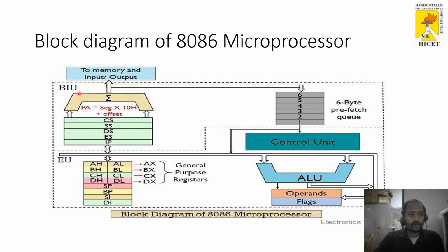Next we discuss the BIU, the bus interface unit, which takes care of all the data and address transfers on the buses for the execution unit, like sending addresses, fetching instructions from the memory, reading data from the ports and memory, as well as writing data to the ports and memory. It has some functional parts such as the instruction queue, segment registers and instruction pointer.